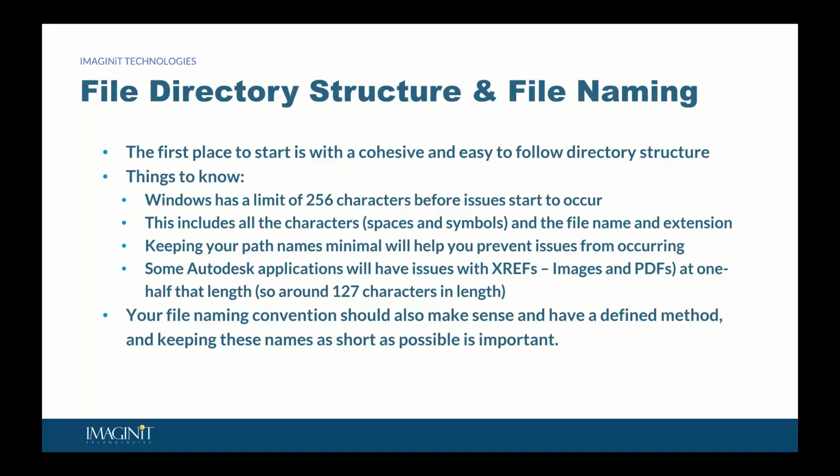So usually in those cases, I may have to move that project shortcut folder closer to the root of that project in order for those data shortcuts to be read correctly. So that comes back to this 256 character limit. So be aware of that limit. A lot of people don't know it, and when you run face first into it, it hurts.